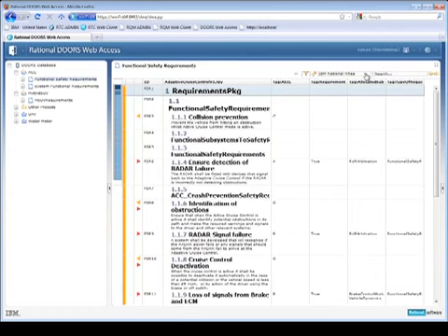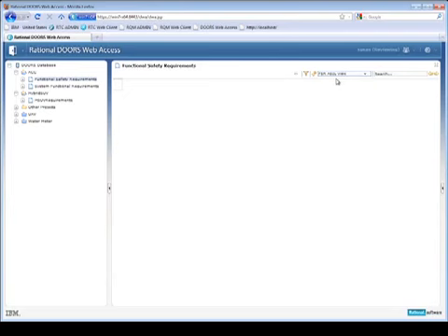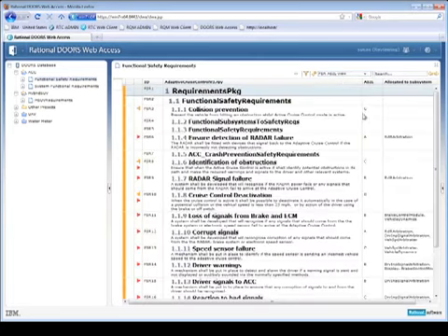Finally, this view can be customized and tidied up, and we're now going to look at a customized view, which is really just showing the functional safety requirements along with the ASIL and the allocated subsystem. These are both requirements for ISO 26262 and can be easily captured within DOORS. Other views can be created which also link requirements through to test cases and test plans and the results of those test cases and test plans.